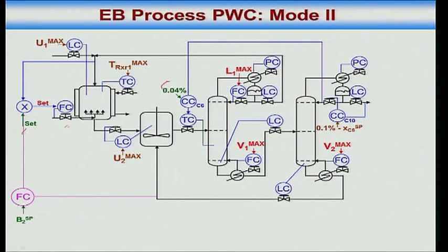We do this. Or you can even control a temperature. If ethyl benzene drops down, this flow will increase. The bottom flow, this flow will increase, if ethyl benzene is dropping down. Composition, I don't want to measure compositions, because composition is the only product purity you will get, nothing else you will get. You are still supposed to operate it without any composition. Temperature, pressures, flows, that's all that's available. Composition very rarely. The only place where people are willing to measure compositions is the product, because that's what they are supposed to sell. They have to guarantee to the customer, so okay, वहाँ पे they'll make some measurements, but the rest is not available.